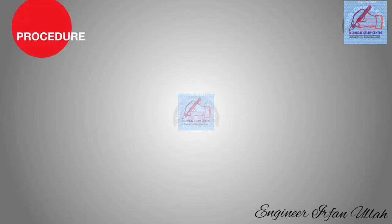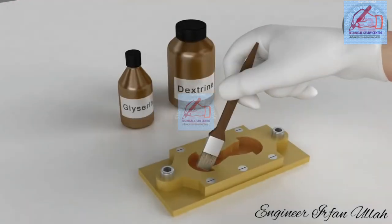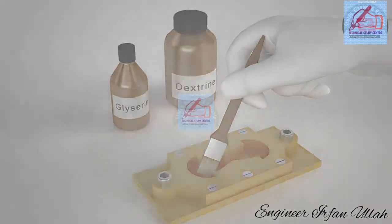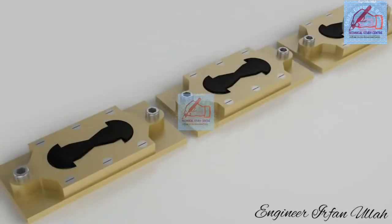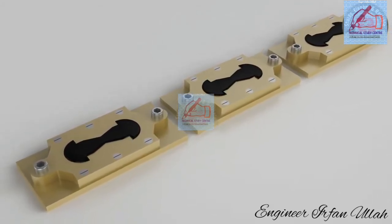Procedure. The bitumen sample is heated to a temperature of 75 to 100 degrees Celsius above the approximate softening point until it is fluid. The solution of glycerine and dextrine is applied at all surfaces of the ductility mold where bitumen is exposed. Now, bitumen is poured into the ductility mold assembly until it is more than level full. A total of 3 specimens of such type are prepared to conduct the test simultaneously.